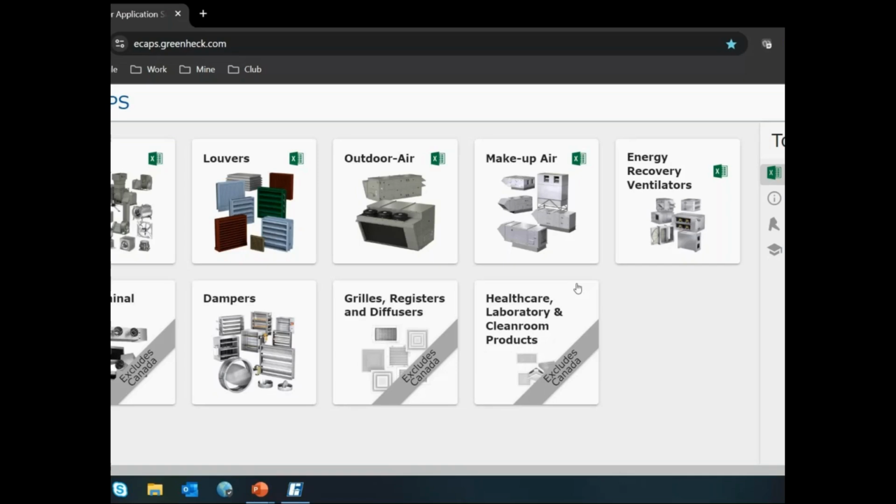And the reality here is much of the time I fix what I can, and then try to speed up the fan for the rest, right? It's going to be a mix. If I'm 15% short on air and I can move the elbow at the inlet 3 feet away, and I've reduced the system effect drastically, so now I'm only 6% short on air, well, now I'm in the range where I can turn that motor up a little bit, or I can turn that VFD up a little bit and get back to my desired goal point.